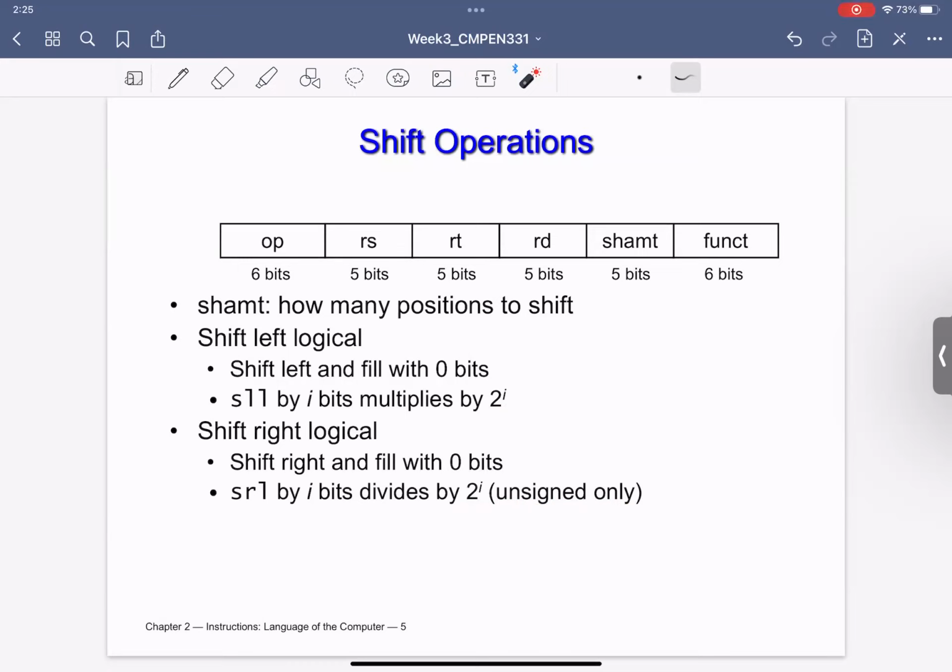And that's why, by the way, we need a shift operation, because in some cases it is a lot easier to do the multiplication by a power of 2 this way than to implement a hardware multiplier. Just for your reference, implementing a multiplier will take a huge area in the FPGA, and we would like to reduce the area as much as we can. This is one of the tricks that we might use in order to substitute a multiplication operation with an easy hardware implementation, which is just the shift.